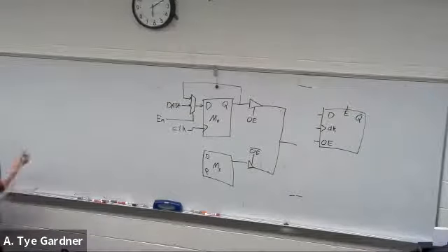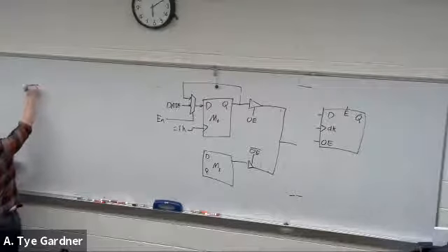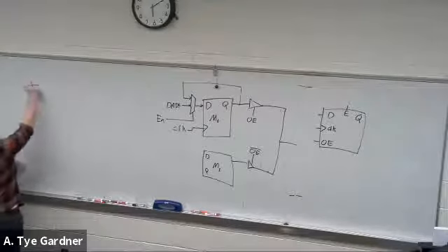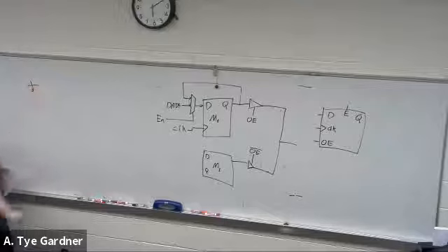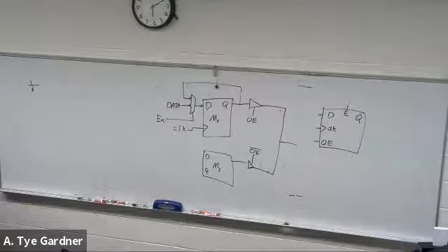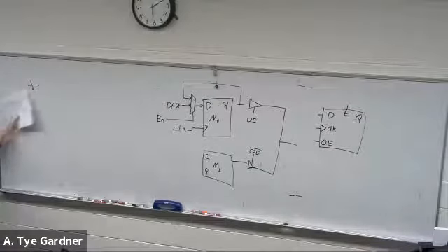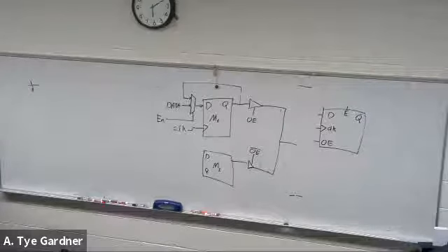So you've seen me, I don't do it often yet, write a slash through a signal and say 8. What this means is this wire is a bus. A bus is really just multiple wires in parallel. And it means that there are 8 bits inside of this guy.